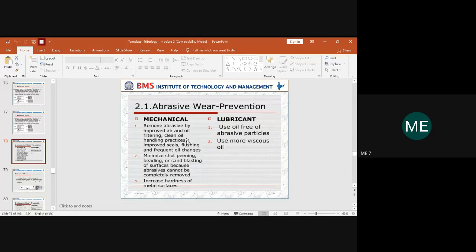You have to make sure that the oil you're using is changed frequently, because sometimes even some scrap, if mixed with the oil and persisting on the hard surface, can result in the formation of wear in the soft material. And it has to be clean. The surface has to be cleaned thoroughly always. If you maintain proper cleaning practices, all these things will help in preventing the formation of asperities across the hard surface.